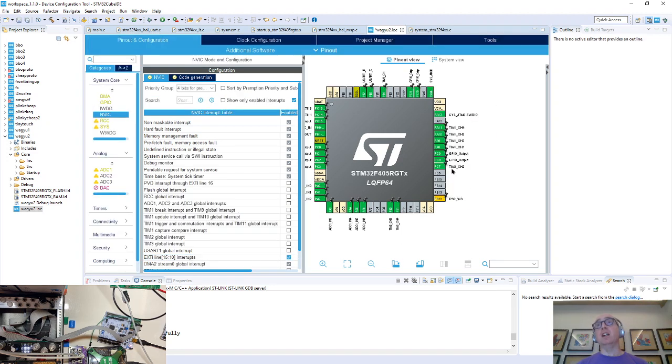So you have the word sync, which is basically... let me see which, they all have different names, so I'm just going to configure them all. I2S data and I2S master clock. So we're going to configure this to spit out a master clock, which basically runs the codec at whatever megahertz it is. Then you have the data, which is basically please play this audio one bit at a time. This is basically an abused SPI peripheral.